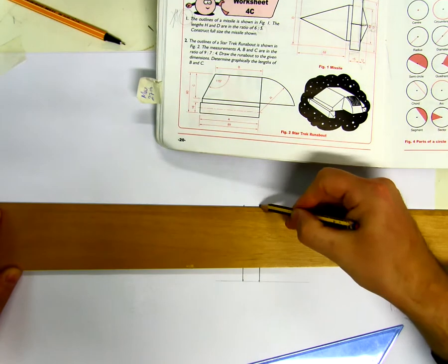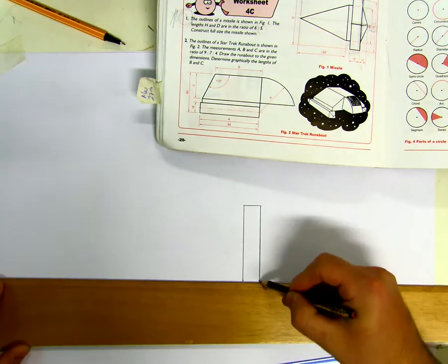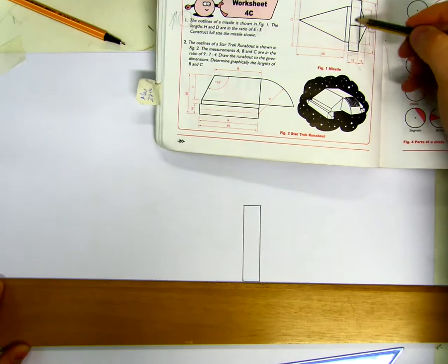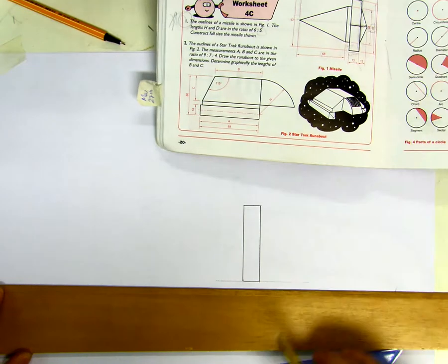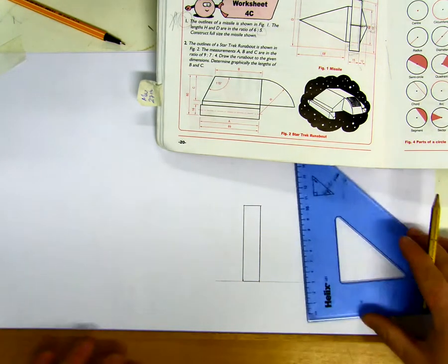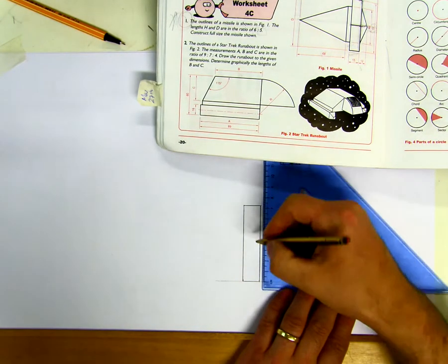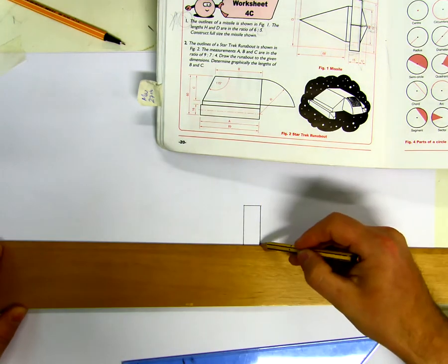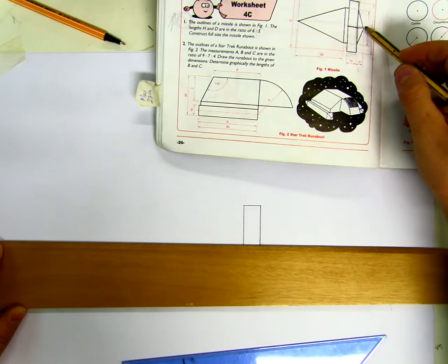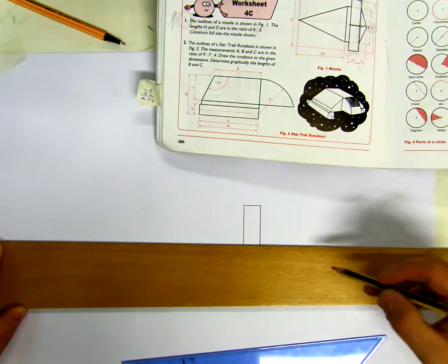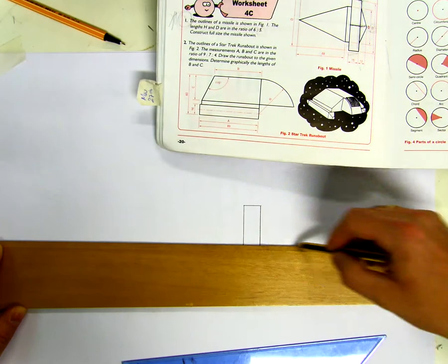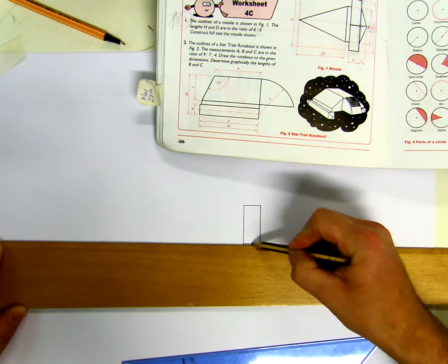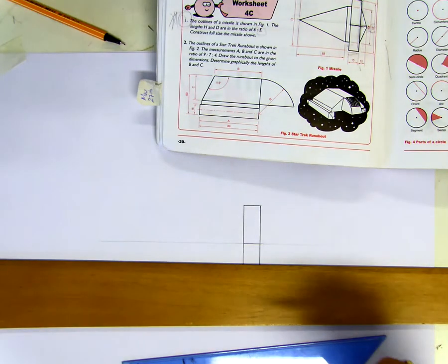Okay, we join them back together. Join that line back together. So we have that bit done. We see there's a line down the middle, so half of 72 is 36. So we find our center line, mark it. We're going to use a construction line really lightly because we can see the end here and the top go through the center. So lightly draw it all the way across, and we can just heavy it in there in the middle.